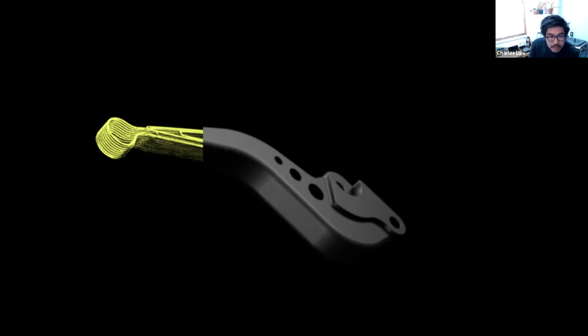How many filaments have a tow of carbon fiber? The tow of carbon fiber is specifically the carbon fiber reinforcement material. The Onyx material does not have a tow within it, right? That is all chopped carbon, whereas the continuous fibers are all tows. If you go to the Markforged webpage, you'll see composite base and continuous fibers. Continuous fibers are all continuous tows.